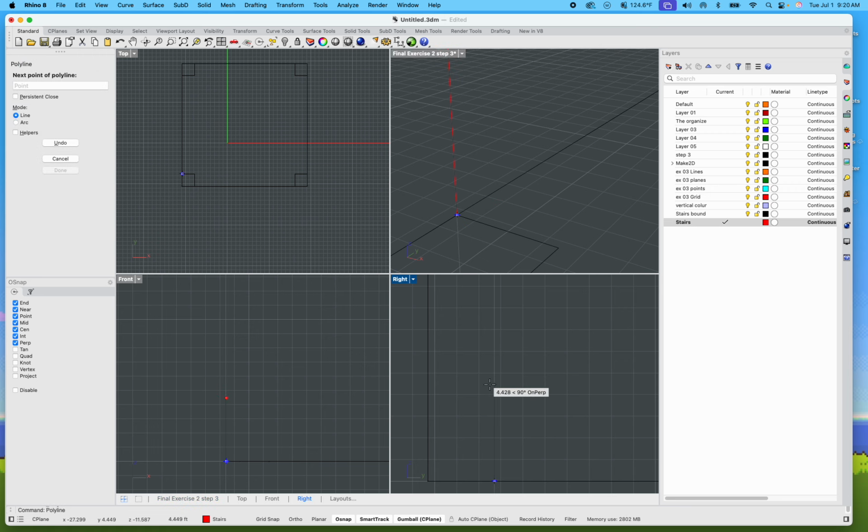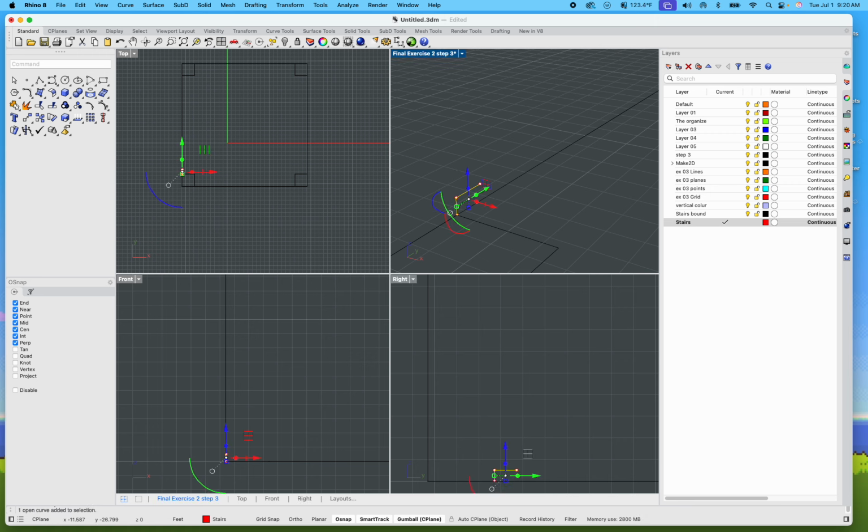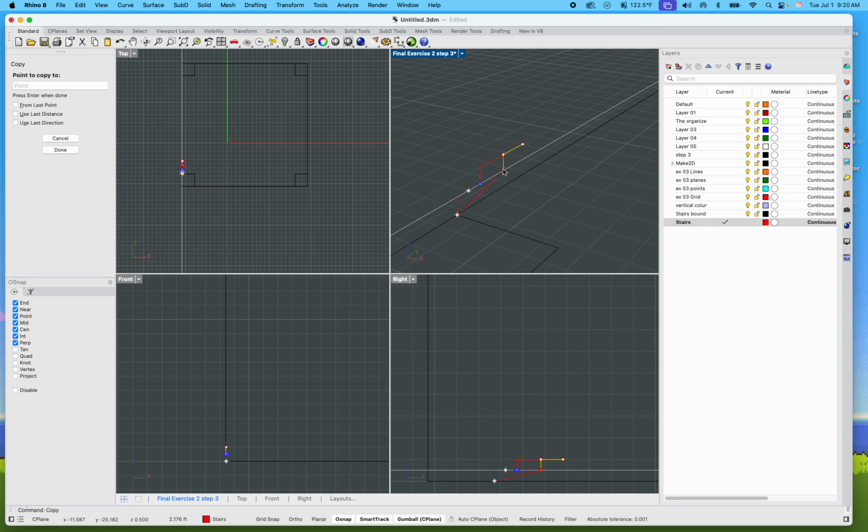So click, 6 inches, enter. I'm going to go to my other view, right? I can hold shift here. 12 inches, enter, hold shift, click. And that's actually, funny enough, all I really need, right? Because I only need one, because, well, why work harder when I can just copy something, select the exact point that I need, and just go to town.